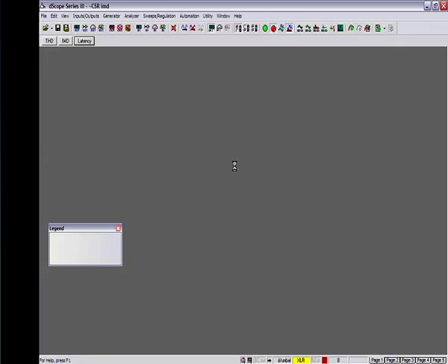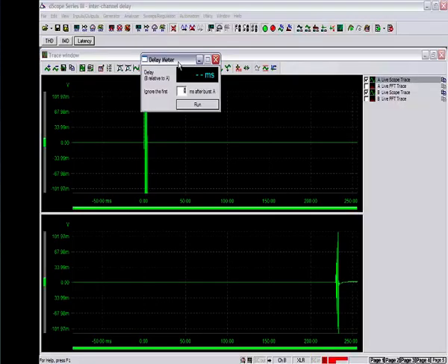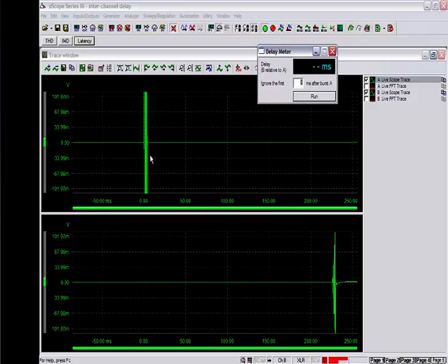So if we just load the test, you can see what we've got here is a very brief chirp. It's only about 5 cycles of a 1 kHz sine wave, which is going into the first 1645 board, and then the bottom trace is what we're getting back from the Bluetooth link. Now if we run the script here, which measures the signal coming back and tells us the latency, you can see we've got about 220 milliseconds of latency here, which is not very good for any kind of real-time applications. It's like if you want an AV headset or for gaming.